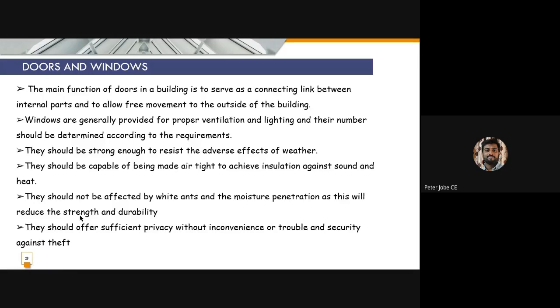So you need to understand that wherever we are providing doors and windows, the door and window frames are not designed to carry loads. So wherever there are doors and window frames, we should provide a lintel above them. That is mandatory, because the load above cannot be transferred safely by using a door or window frame. They are not designed to do so. Lintel means a reinforced beam, we can say, and what it will do is take the load from above and distribute it to the walls.